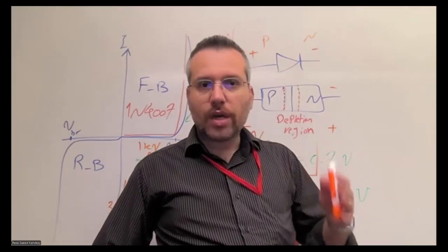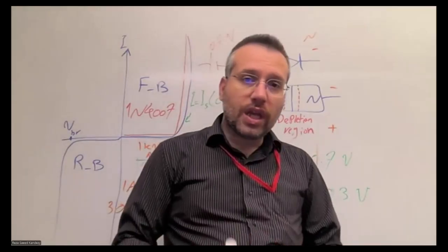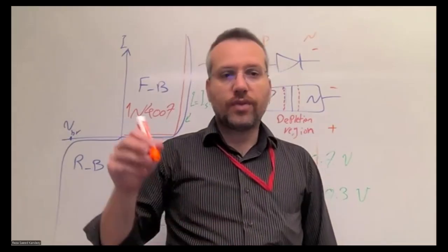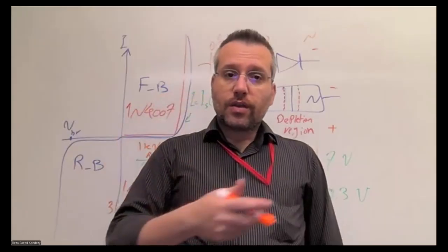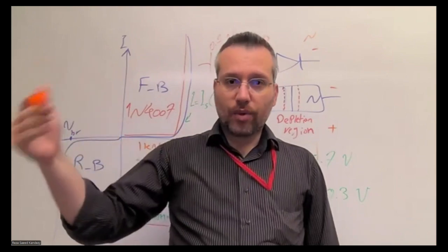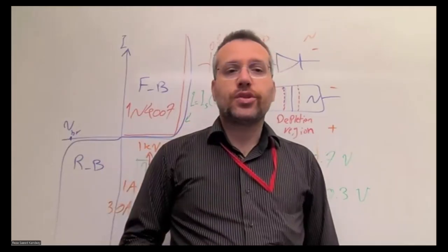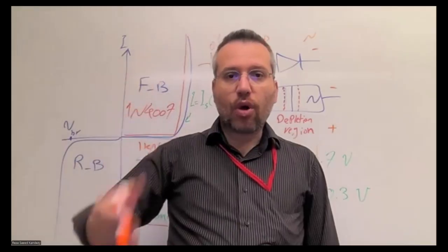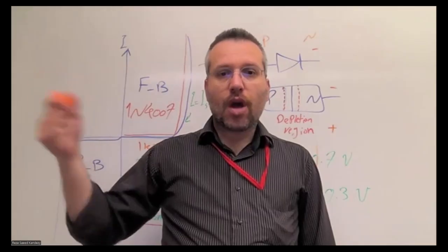Now, to summarize, the diode conducts significantly only when it's in forward bias and above the voltage on threshold. Its current rises exponentially after that point, but for most practical circuits, we assume a constant voltage across the diode.